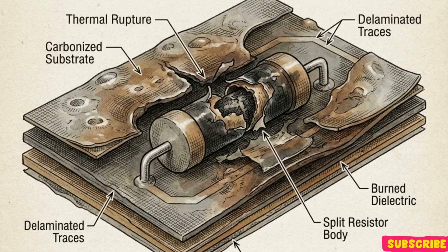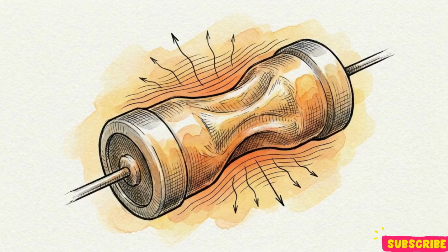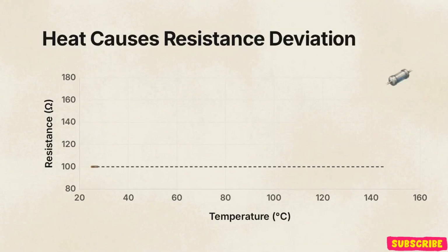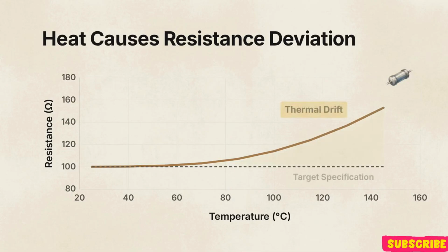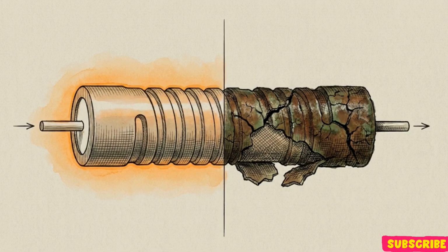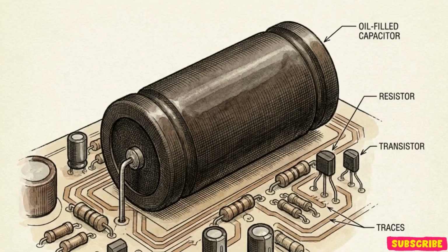While heat generation is the intended function of the component, unmanaged thermal load destroys the physical material. If the temperature climbs too high, it triggers thermal drift. The excess heat alters the intrinsic electrical properties of the conductive material, shifting the internal resistance value away from its intended specification. Resistor design is a constant physical battle to stabilize intentional energy conversion while preventing the material from degrading. Early circuit designs managed this thermal threat with a brute force solution, the carbon composition resistor.